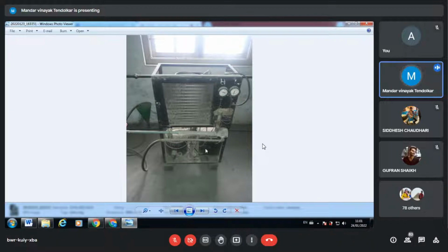Right? Here, since the water is flowing, we will be measuring TW1, that is inlet, and TW2, that is exit. So m dot into Cp into delta T. Logic is same. Theirs is a stored one. Ours is a flowing one. And why we made it flowing? Because we will directly get the reading in watt or kilowatt, because it is time derivative.